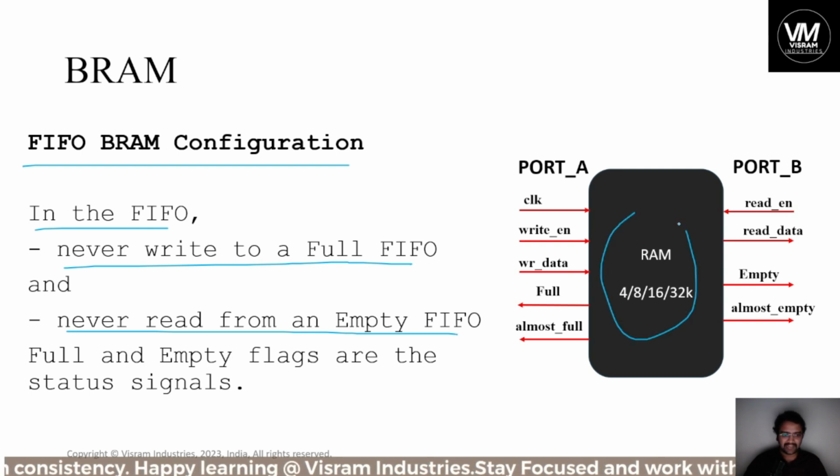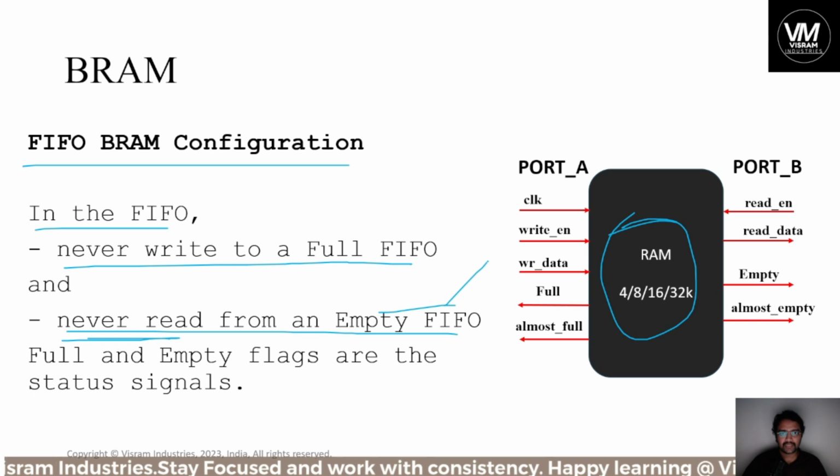See, if this entire BRAM is a FIFO now, if you have zero values, what will you read? You can't read anything. That is what the meaning is. Never read from an empty FIFO. I would suggest you understand this in your local language, whatever place you come from, but it will be very helpful if you realize this entire subject in your own terms, your own language.